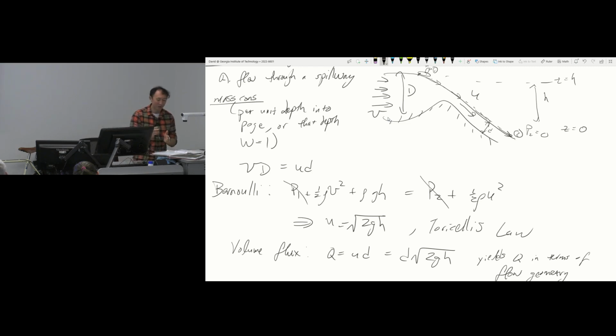But this is basically the only way to solve. The Navier-Stokes equation you can solve in a couple of limits. You can solve what we just did, which is the unidirectional limit, where the flow and the velocity gradient are perpendicular. That you solve in 2 or 3 problems. Now we're going to solve for a flow where there's no viscosity. And if there were more time in the course, we'd do a whole homework on low Reynolds number stuff. But I have a feeling we're not going to get to it.